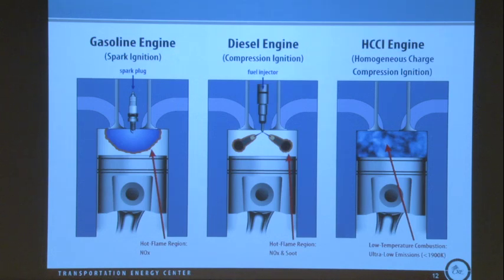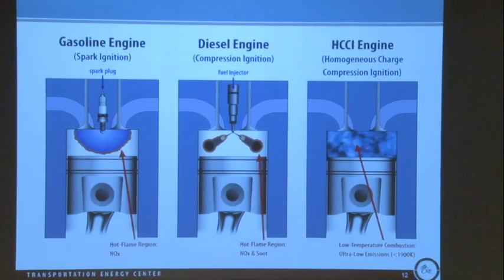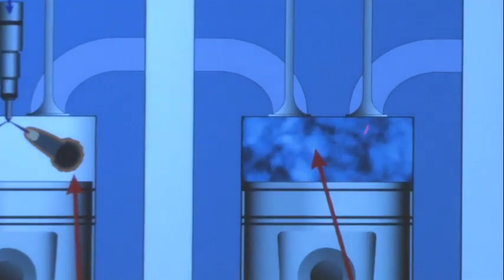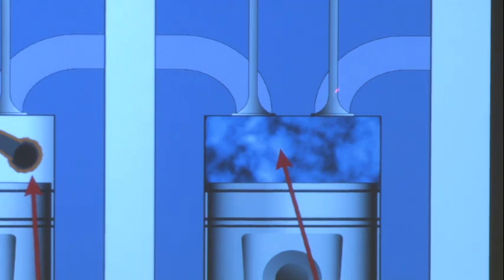So the challenge has been how to decide when to start ignition relative to the piston motion isentropic compression process, and then the subsequent combustion rate after it ignites. So you want to control that by various means of creating thermal stratification, hot pockets with cold pockets, or composition stratification, through different mixing processes in the chamber through tumble and swirling motions, or through multiple injections of fuels that have different reactivity properties.